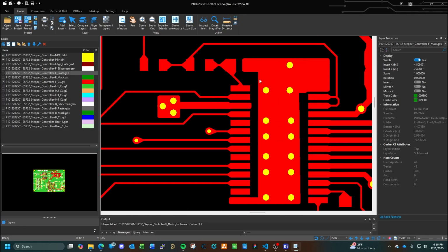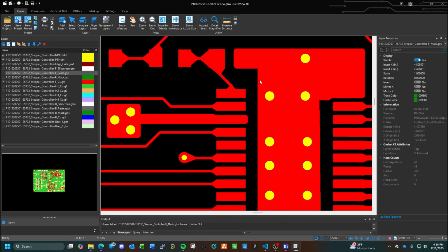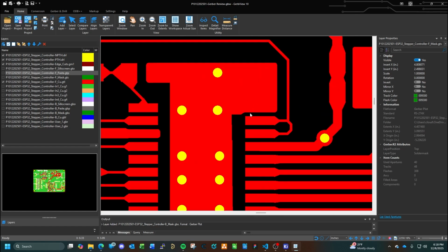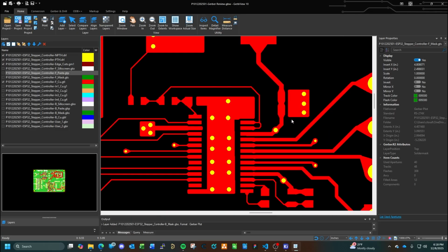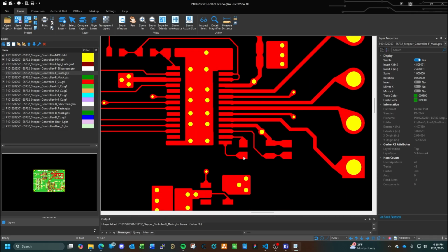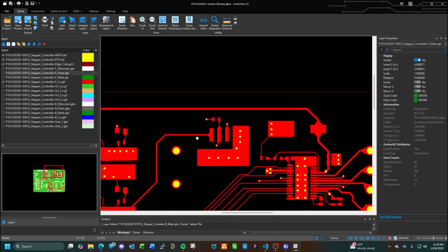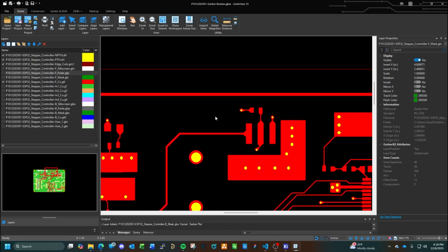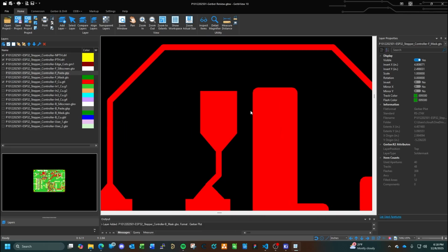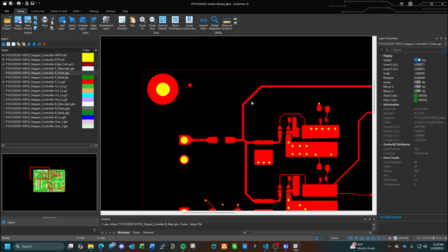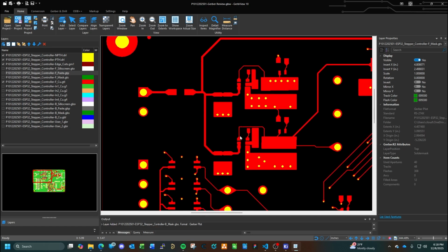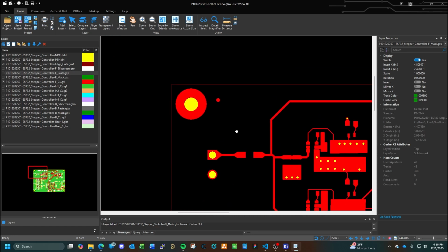Now we're going to look at the copper layers. We want to make sure that when KiCad generated the Gerber files, it didn't accidentally encroach any plane or any copper pour onto a pad it wasn't supposed to, that there's no stray lines, no stray connections, no stubs. That nothing got mixed. So it's just a really cursory review of how the Gerber file was generated. It's going to be more of a testament to how it's going to be manufactured in the long run by the vendor house, by the PCB house.